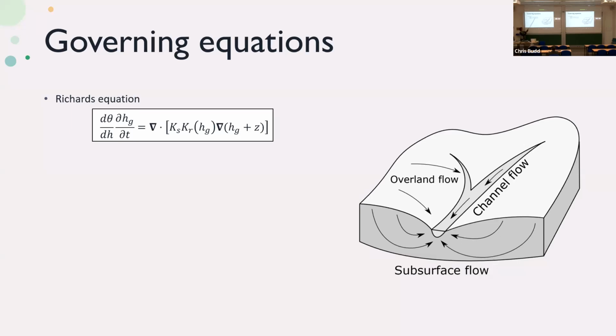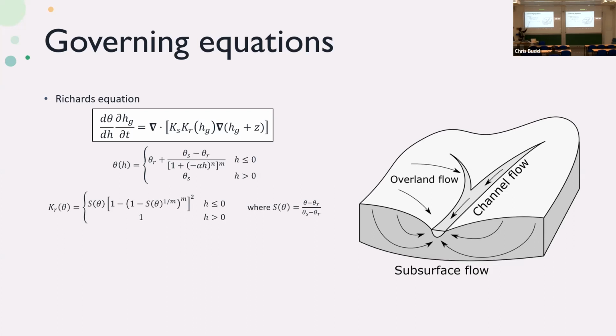So it's proportional to the gradient of pressure times a constant which is called the hydraulic conductivity, which is not necessarily constant because it may depend also on the pressure, measured by hydraulic head h here, especially in the unsaturated soil, in which the water doesn't fill all the pores. And the functions here, theta and K, are highly nonlinear functions of this pressure head h.